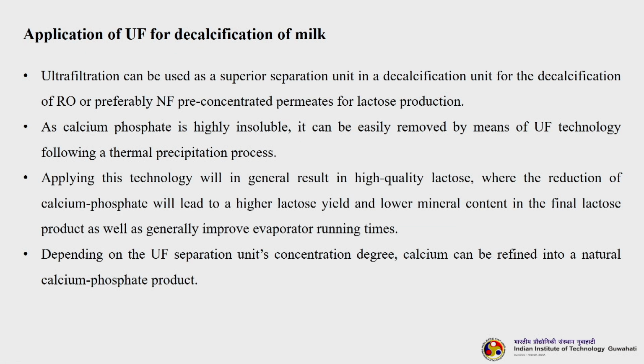Then, application of ultrafiltration for decalcification of milk. Ultrafiltration can be used as a superior separation unit in a decalcification unit for the decalcification of RO, or preferably NF, pre-concentrated permeate for lactose production. So, you are removing calcium, actually.